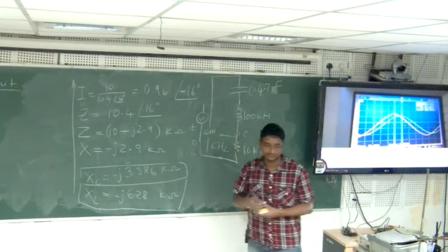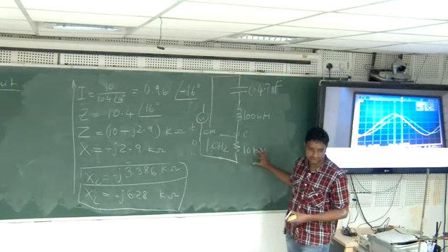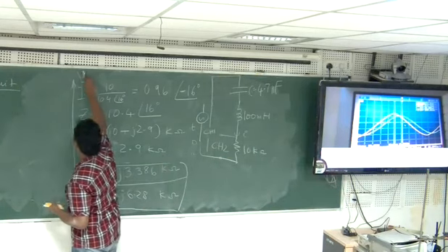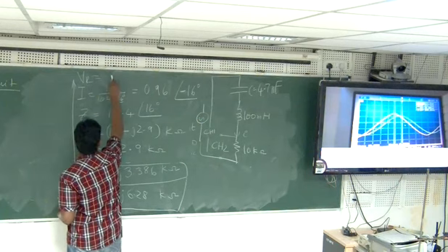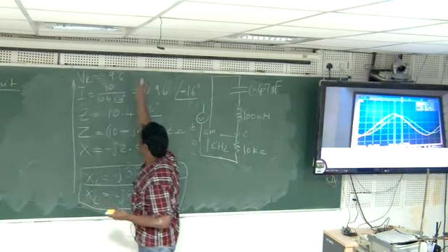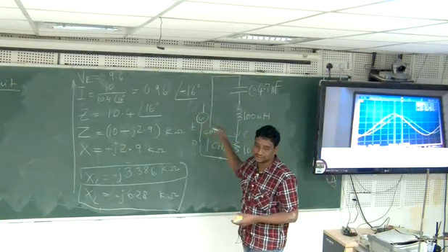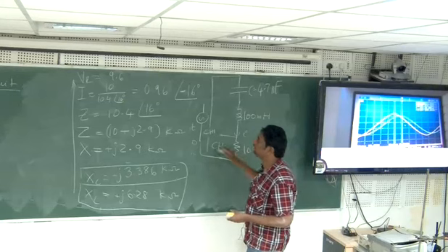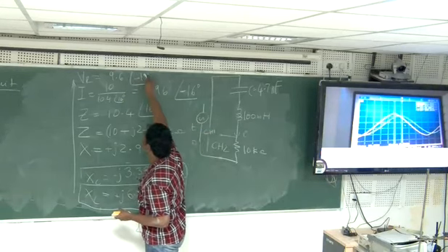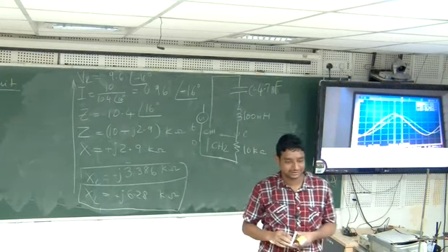Now if I still do this same channel to measure voltage across this one, I am expecting my VR, voltage of resistance, will be 9.6 volts, because the kilo ohms and milliamperes will cancel out with each other, and then 10 into 0.96 is 9.6 volts, and the angle will be minus 16 degrees. So minus 16 degrees is how many microseconds?